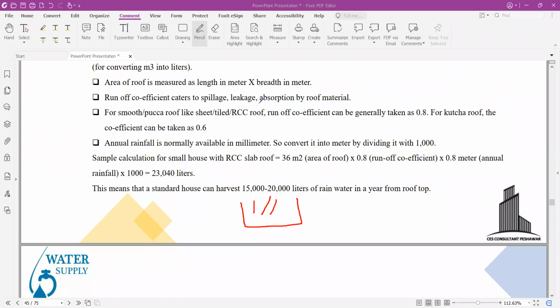How about the terminal pressure? Will you be discussing the terminal pressure in the design? Inshallah, we will be discussing it in a consequent lecture. Basically, when we discuss the Pakistan standards, we will discuss what minimum pressure and what maximum pressure should be provided at the junction. Mostly about 20 psi is the minimum pressure and 80 psi is the maximum pressure provided at the junction.